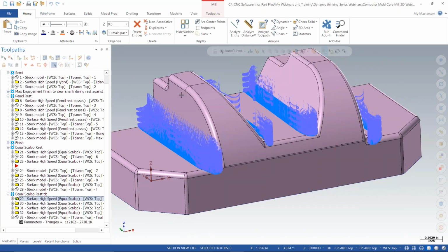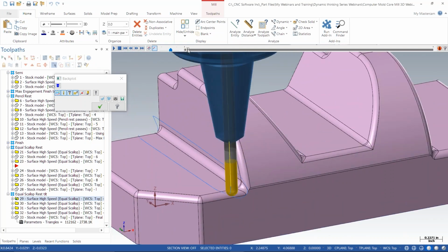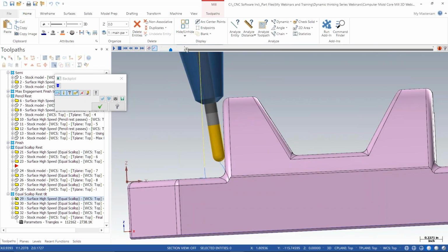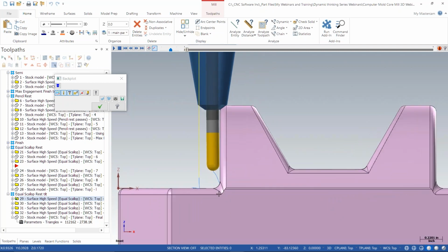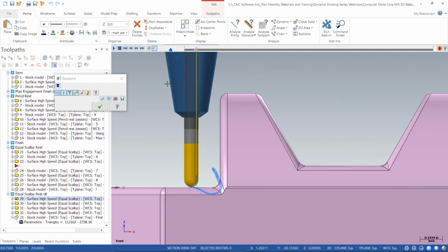And then this one here, like any other example, I couldn't help it, but I'd like to show that I could also, because this is a vertical wall, if this was a real condition you were concerned about and you didn't relieve your tool, there's no relief on the wall, don't forget we have tilt, right? I just turn on the tilt and now I got a multi-axis method to dig out these corners.